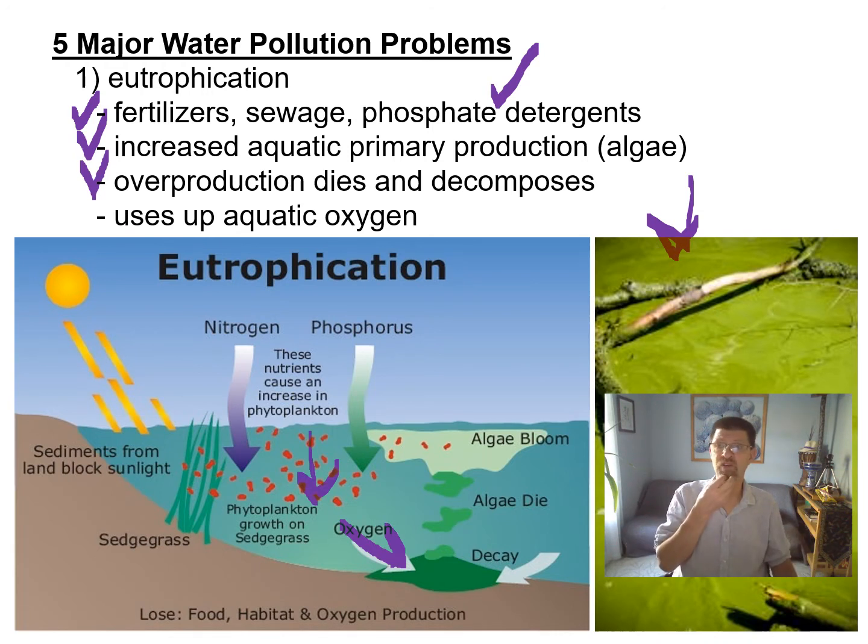If you've been to a golf course where they use a lot of fertilizers and a lot of chemicals that keep the grass really green, one of the things they have to do at a golf course is they have to put pipes down into the bottom of those water hazards and bubble air up through a pipe. And what that does is it keeps the water mixing so these nutrients get spread out. It is an effort to avoid eutrophication.